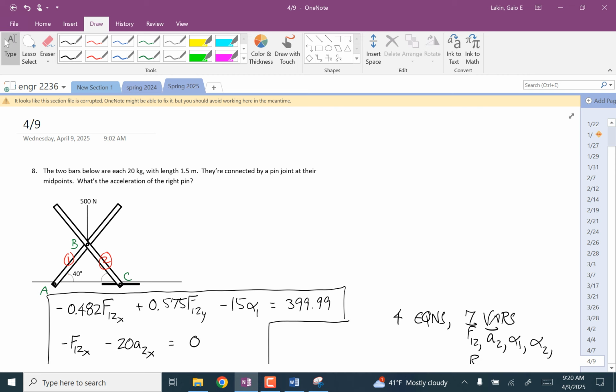Because there's a million things you could do to this to make it accelerate horizontally. But there's nothing you could do to this to make that pin accelerate vertically. And that's what we're doing. We're saying that slot, no matter what you do, doesn't allow this pin to move vertically. Okay.